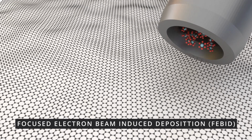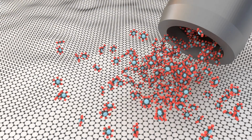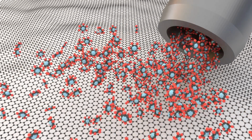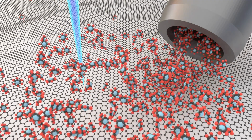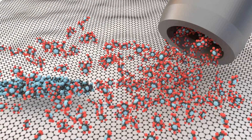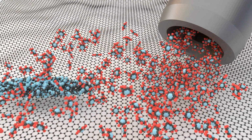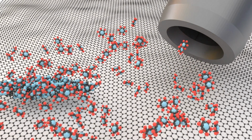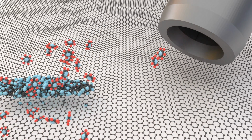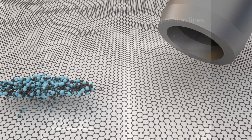In this process, a precursor gas, composed of molecules that contain a single platinum atom, is injected across the sample surface in a scanning electron microscope. The imparted energy from the electron beam is able to break these precursor molecules apart. The molecular fragments are chemically reactive and spontaneously bond to the nearest object. The electron beam, therefore, can be used to directly write on a surface with this technique.